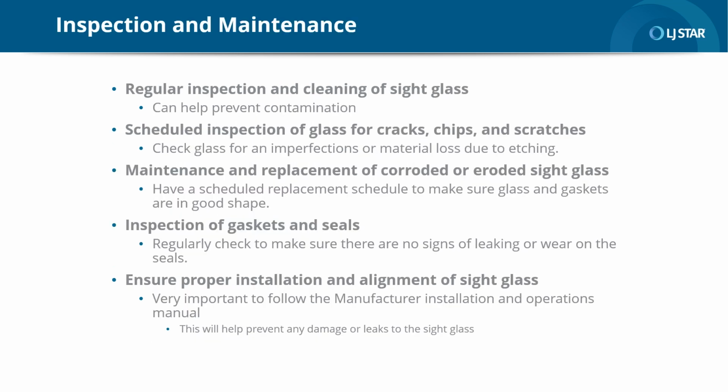Inspection and maintenance is extremely important and something that I really stress to our customers, because regular inspection and cleaning of the sight glass should be done, so that you can actually properly see the sight glass, that it's well maintained, and you have some sort of an idea of what's happening over time. I like to see an inspection and cleaning schedule. I know that not everyone does it, but I highly recommend, as does LJ Star, that you have a regular inspection period with regards to cleaning of the sight glass.